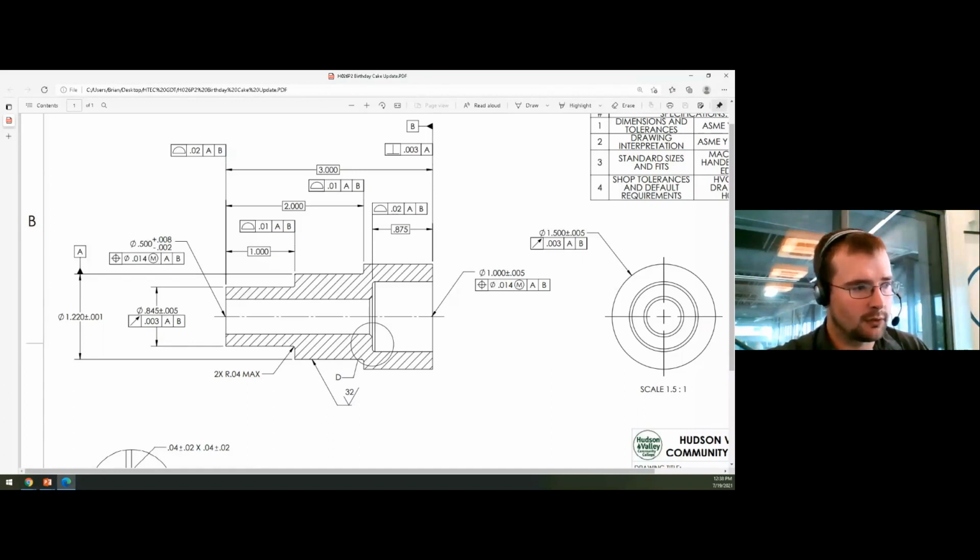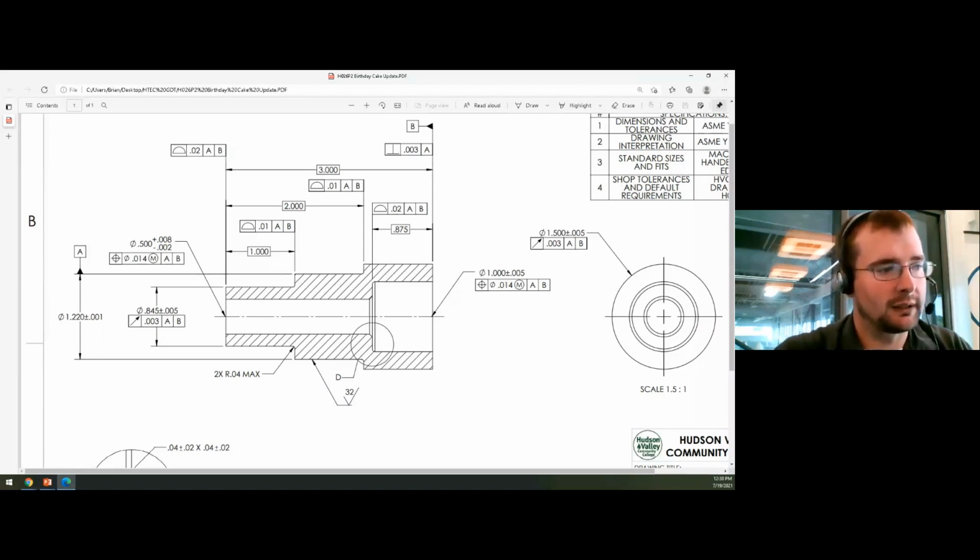Again, material costs are always an issue. So we did standardize with 2-inch round stock for most of our turning work for any general learning. If it's a specific project, we do have a couple of parts that require 3 or 4-inch aluminum and or steel, depending on what class it is. But for most of the early projects, for turning at least, we bounce around with 2-inch aluminum, 2-inch steel, 2-inch stainless, 2-inch cast iron, brass, whatever.